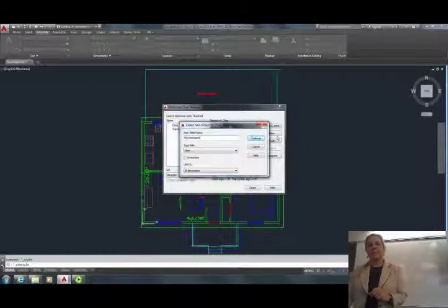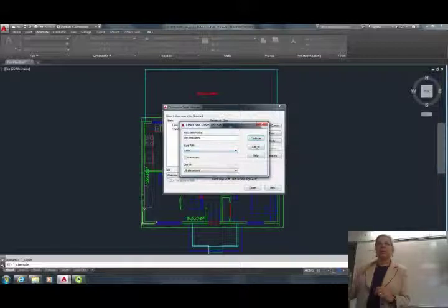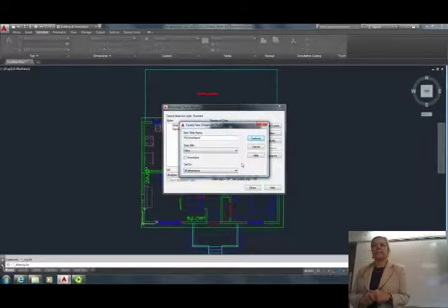Once I have a dimension style set up, I copy-paste any dimension from one file to the other. Because guess what? When you take any dimension and bring it to another file, it brings the style with it. Very easy. Idiot-proof. Lovely way of cheating or speeding up the project.